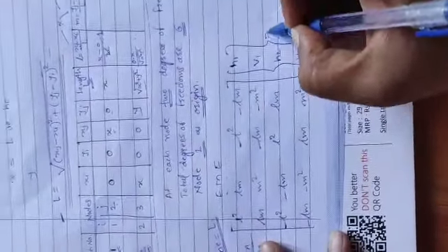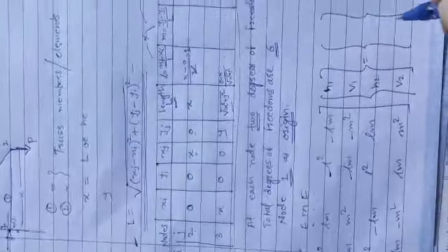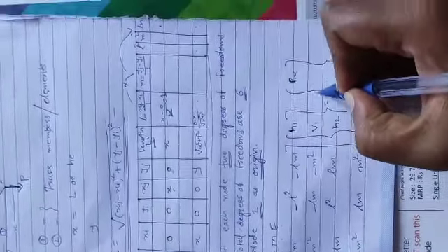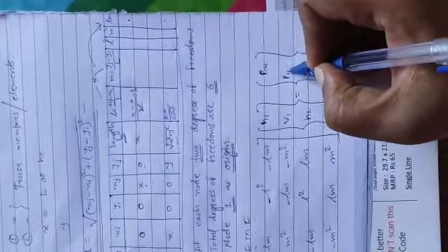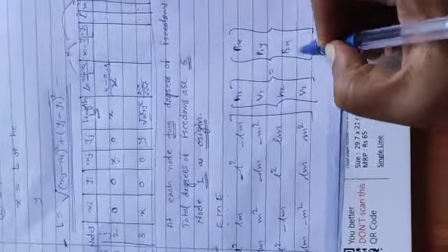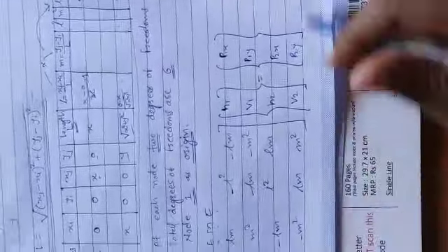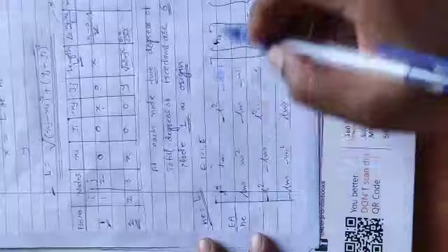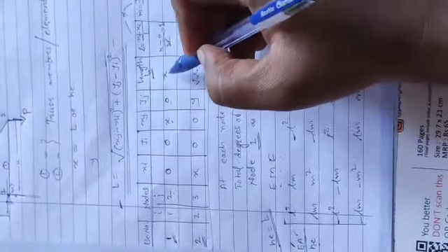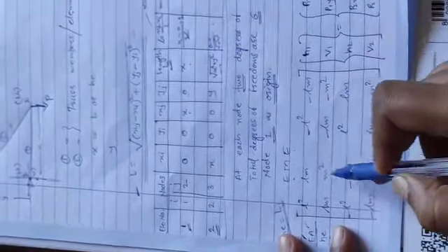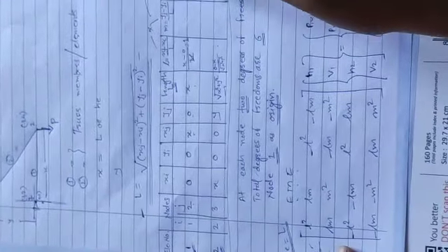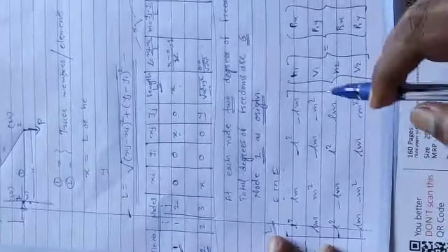h1, v1, h2, v2, which is equal to p1x, p1y, p2x, p2y. We know all these things. E is modulus of elasticity, A is area which is given, then h is length of element. Okay. Then l square, lm, m square, all those values are written from this table.